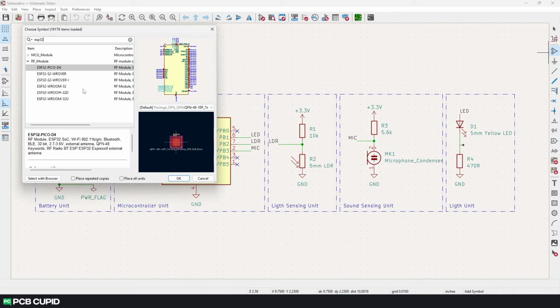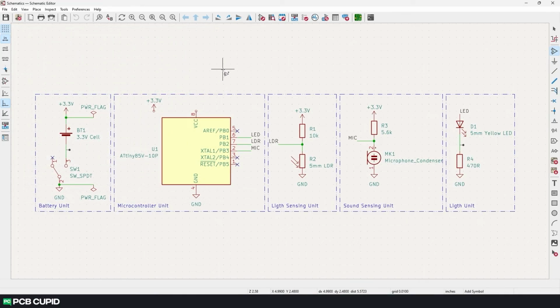I would always prefer to make a custom symbol because it will reduce the unknown variables that are introduced to the circuit. But once you find a reliable source to get your symbol and footprints, it will reduce a ton of work down the road. Fortunately or unfortunately for this particular circuit, we might not need to create custom symbols. So we'll try to recreate one of the existing symbols to learn how to use the symbol editor and learn how to make custom symbols.